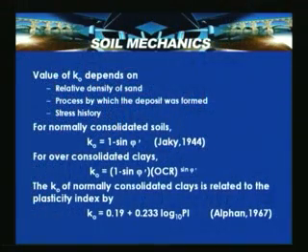Before venturing into this, let us review what we discussed. We discussed that the earth pressure coefficient K naught depends upon the relative density of sand, the process by which the deposit was formed, and the stress history. It can be estimated using Jaky's formula, which for normally consolidated soils is K naught equal to 1 minus sin phi dash.